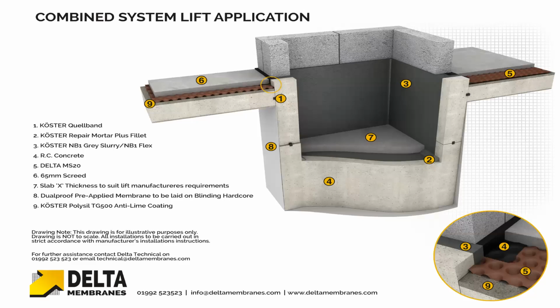Lift pits, the bane of my life. So lift pits, always the lowest part of the building. We can't line them with cavity drainage systems for obvious reasons, because of the plant and fuel and all the fixings and stuff like that. So we have a Type A system on the outside, a reinforced concrete structure with water bars in it, and we have another Type A system on the inside. Okay, so we're really kind of going to town on levels of protection. So 2 waterproofing membranes and a structure which is integrally water resistant as well.